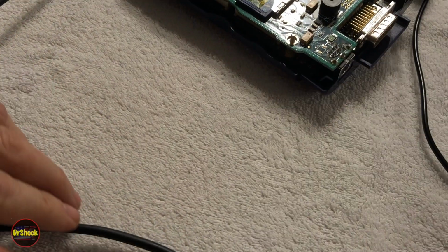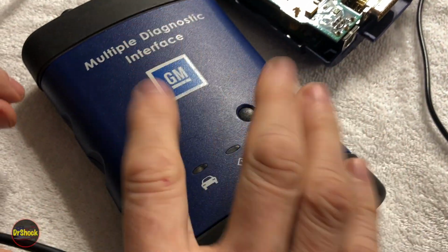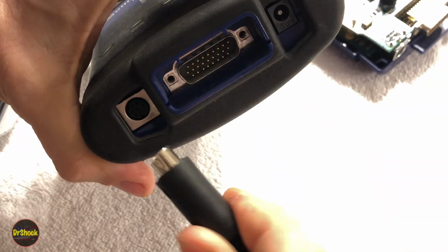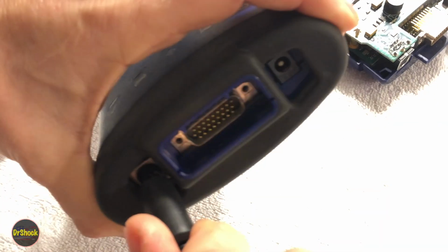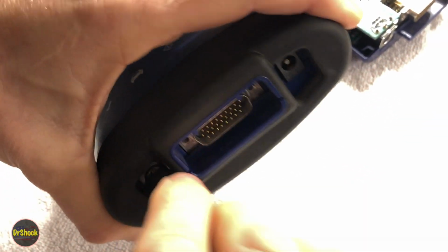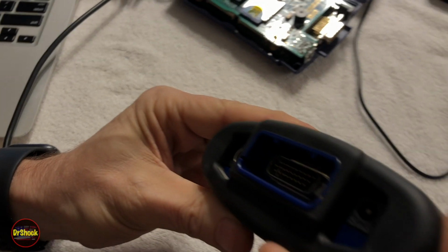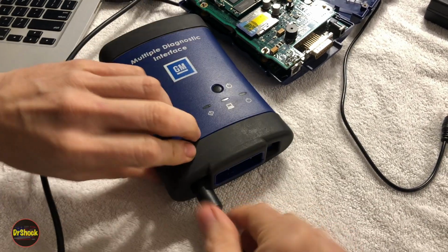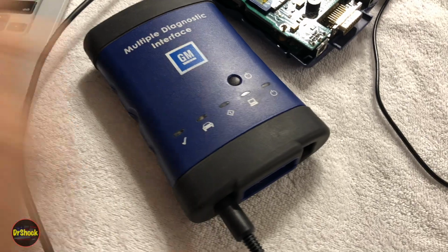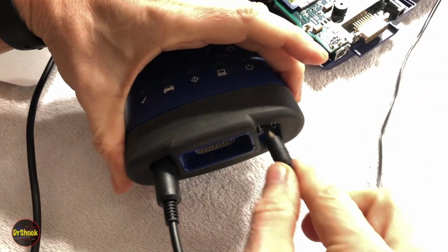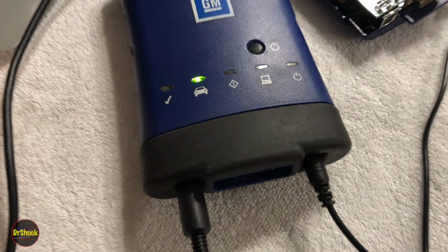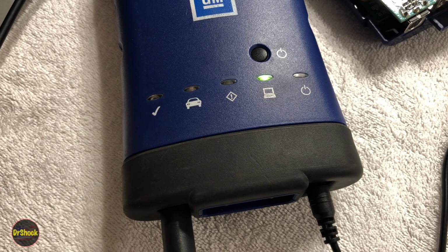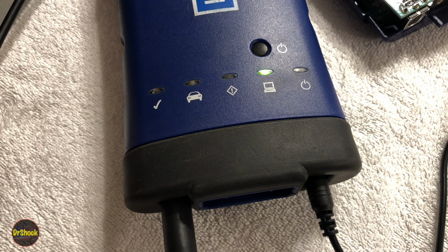Now we went ahead and reflowed the CPU board for this genuine one as well. Always have trouble seeing where the little notch is on this guy. To get this mini DIN in here, we'll go ahead and clear the data on the computer, and we'll see. I already put this one back together. So now with this guy, same test, and again we didn't touch the FPGA board, we just reflowed the CPU board.